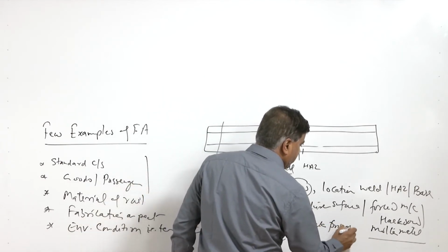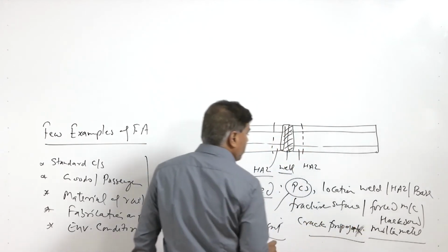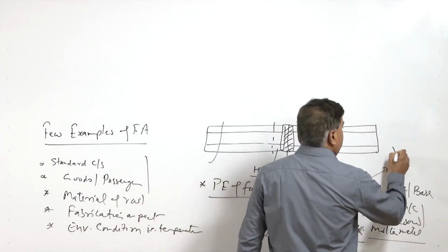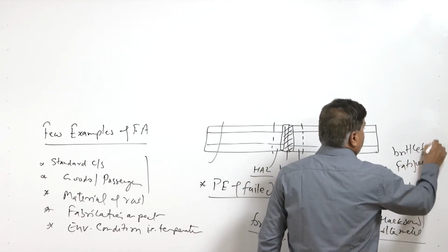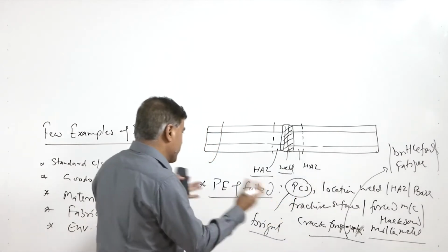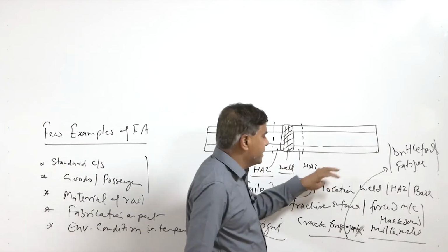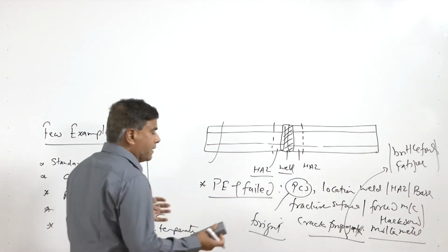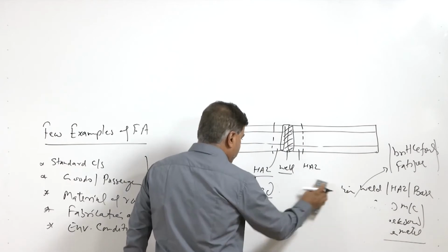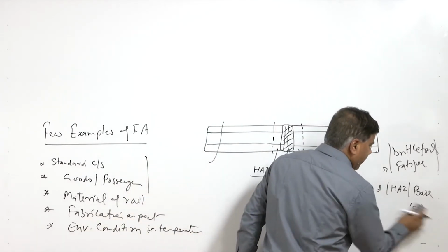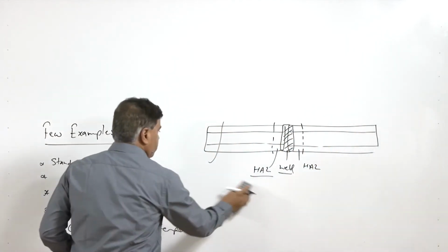This crack propagation, whether it has been sudden, whether the crack propagation which has caused the failure was in the form of a brittle fracture or it was a fatigue fracture. So, that also we need to establish as per the case. The location from where the failure has taken place will certainly provide greater directions and possibilities for the failure analysis. So, this is what we will have an idea of from the preliminary examination of the failed component.